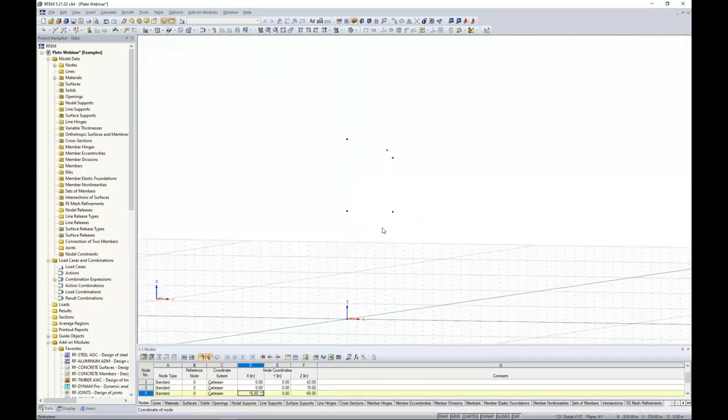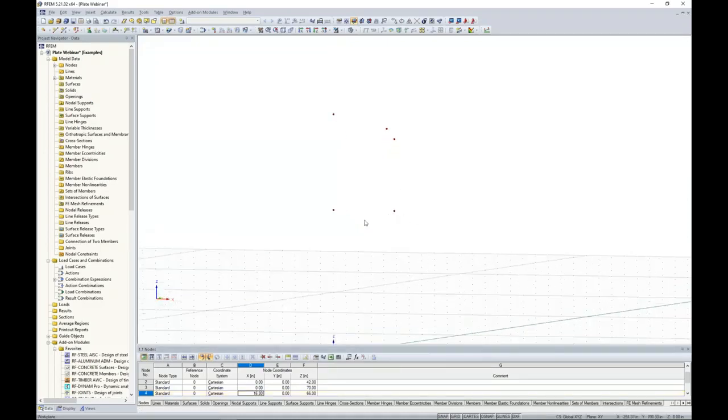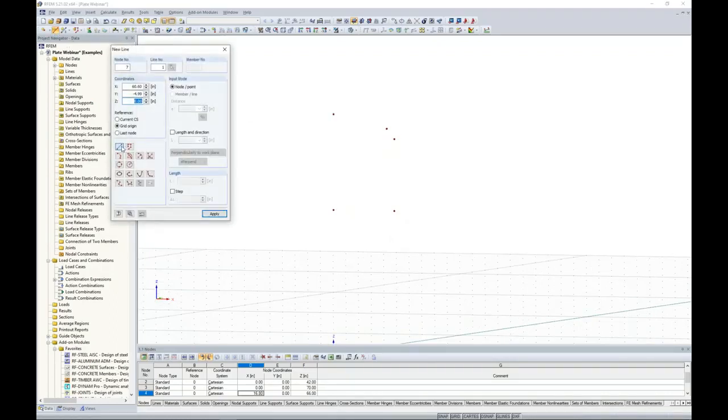And they don't really mean too much right now, but what we want to do is to connect these nodes with line elements. And for this, I will go to the option up here, my tools, to draw a new line. The first line segment will just be a simple straight line where I'm going to connect this bottom node to this top node. But my next line element, I would actually like it to be an arc.